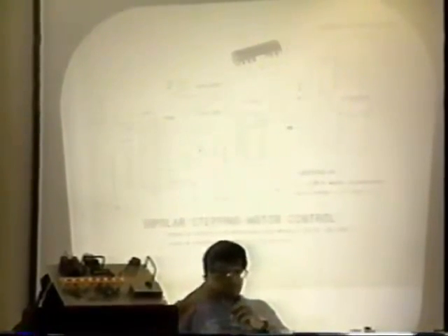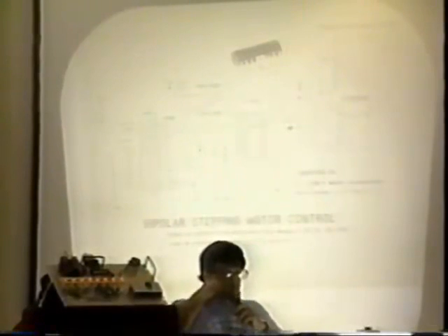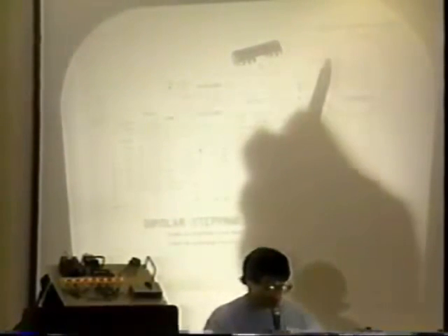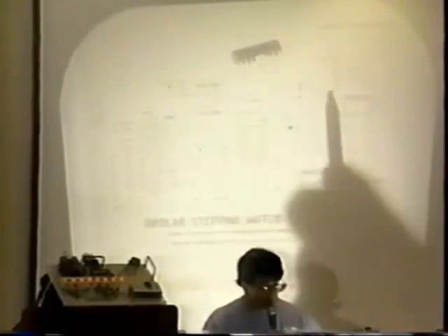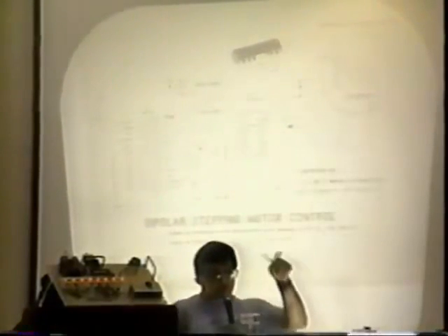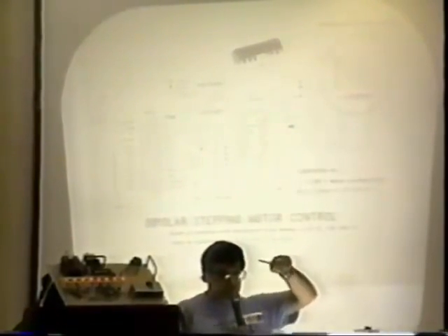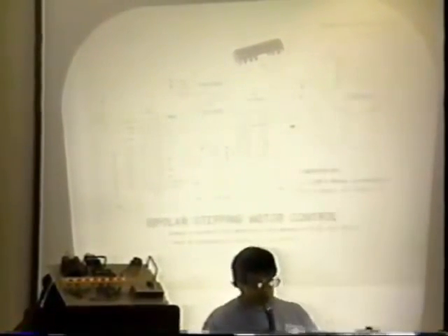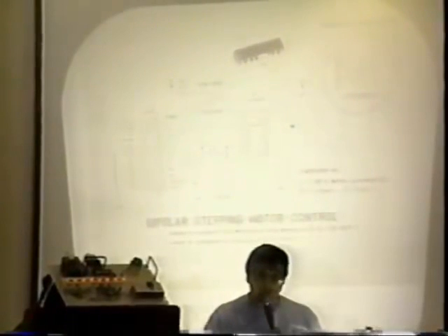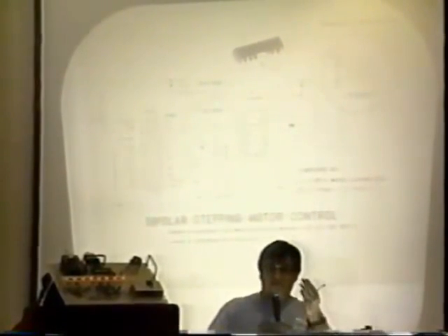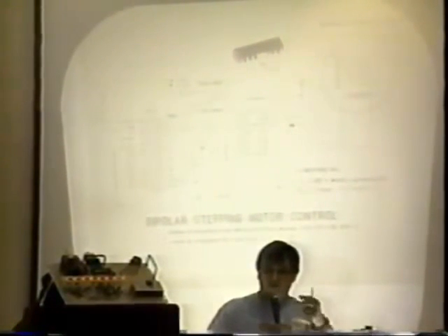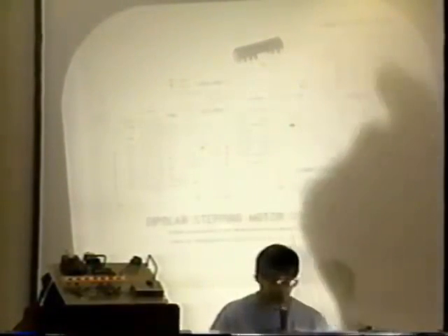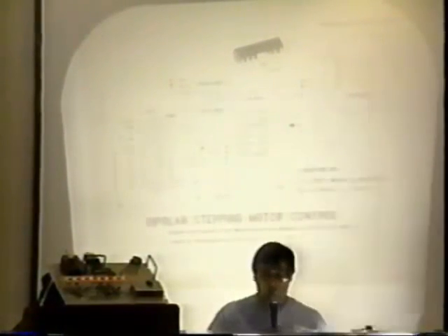But a very special stepping motor is called bipolar. What that means is I can send electricity in this direction, and then I can send it in the other direction, and this thing will move and increment each time. The reason bipolars are so much more popular than the kind that have 4 windings is because you're using 4 times as much power to run as one that has 1 winding of the 4 running at once. Here I'm using all the windings all the time, so I get a lot more strength from a little motor.